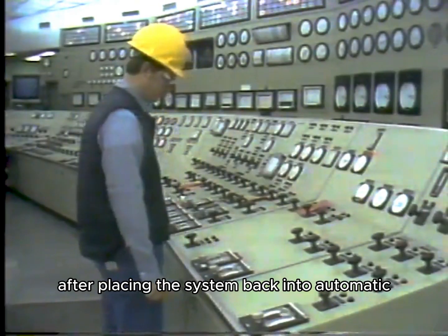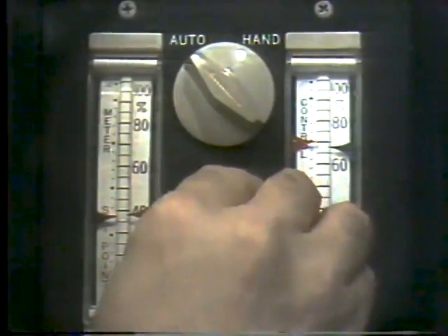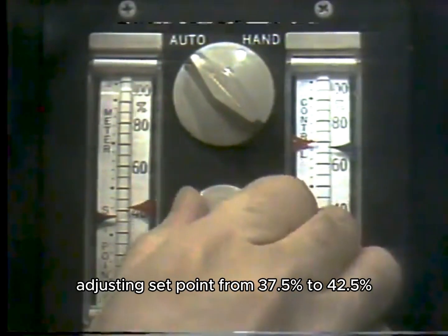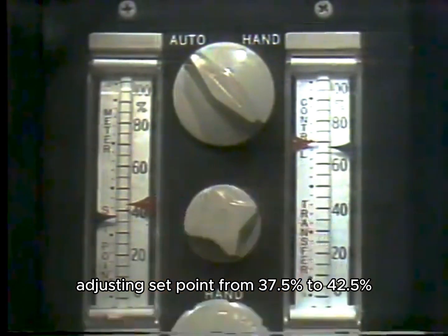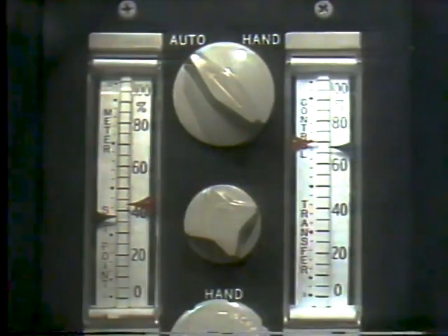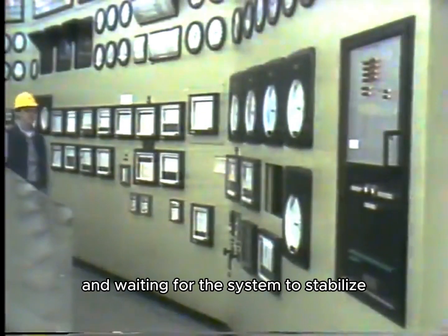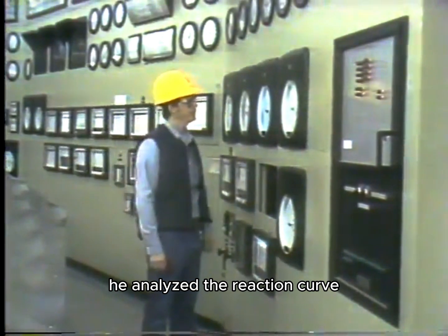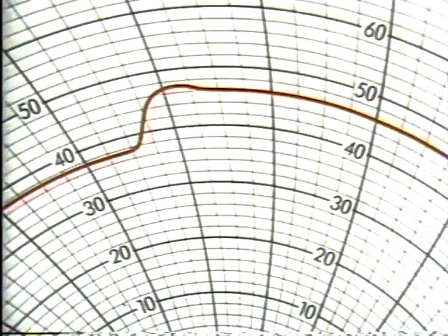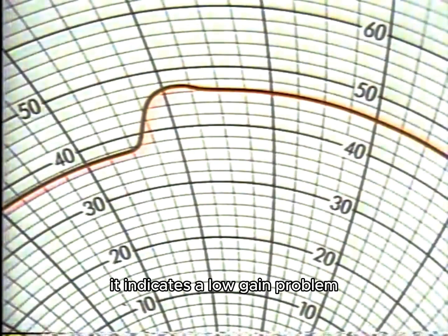After placing the system back into automatic, adjusting set point from 37.5% to 42.5%, and waiting for the system to stabilize, he analyzed the reaction curve. This is an illustration of what the technician saw. It indicates a low gain problem.